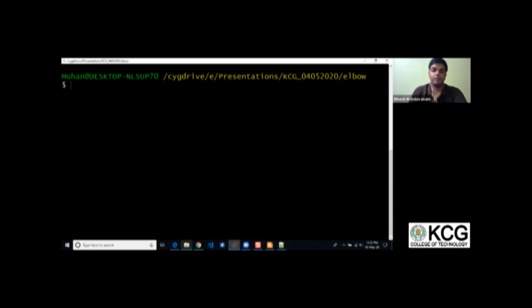Now I'm going to start it fresh in the command prompt. I have converted the mesh beforehand, so I just want to execute it. The solver which I'm going to use is icoFoam. If I go to this particular directory and enter icoFoam, it is going to start solving it. I'm going to press enter, and you need to wait for it.